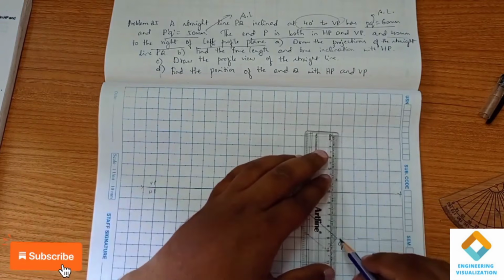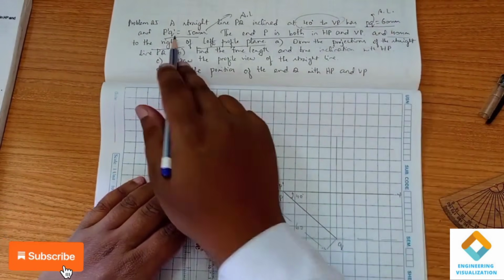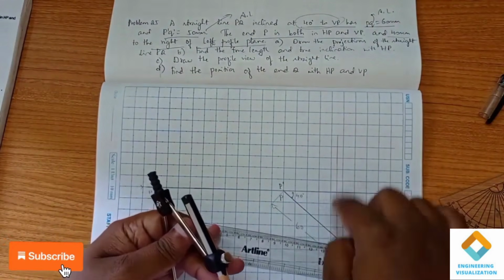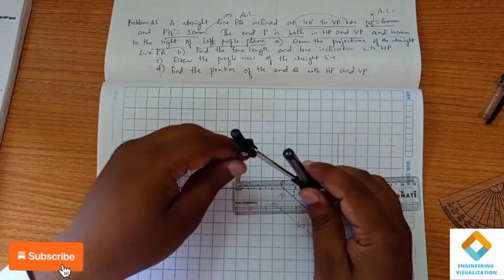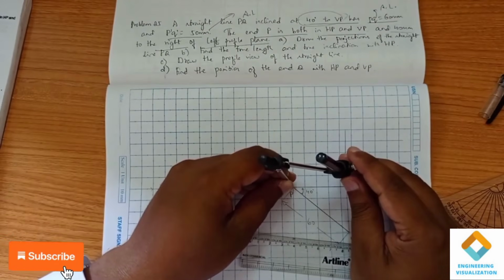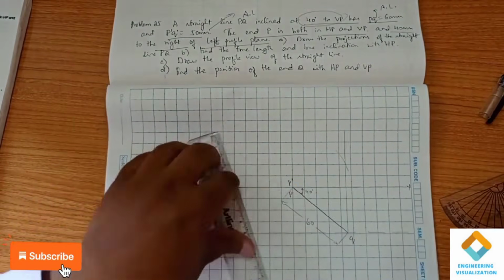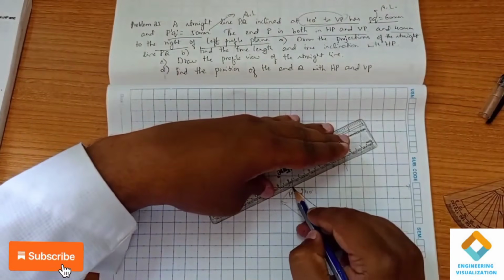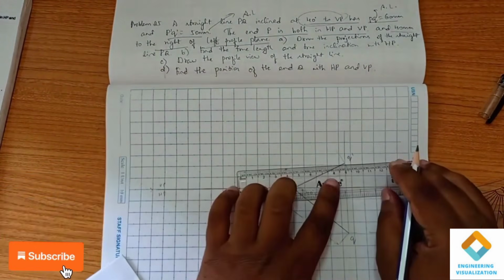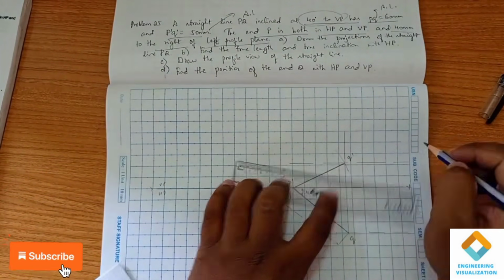We know that PQ is 60 and P dash Q dash is 50. We know that upper end lengths will be falling in a straight line. So now I am measuring 50 mm from the scale. Measuring 50 from the scale, I am cutting the arc here. This is P dash Q dash, and here we have the locus line.